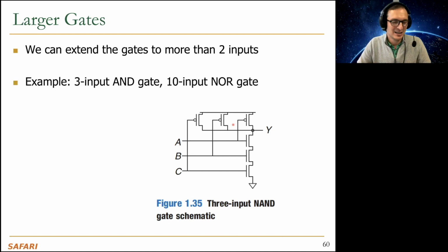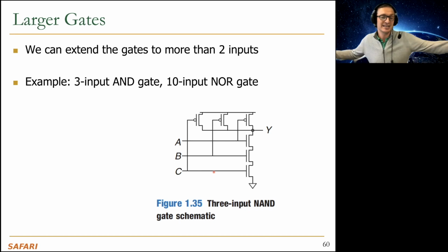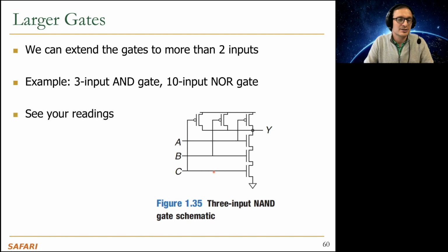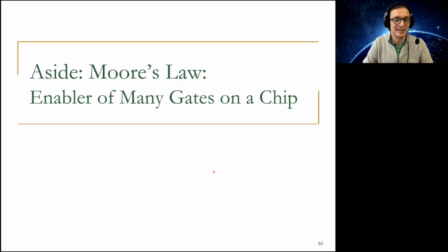Keep on adding. Of course, the downside is that it becomes slower as you keep adding more inputs. So sometimes it's better to construct multiple-input NAND gates from multiple smaller-input NAND gates, as opposed to building one large 10-input NAND gate, for example. Okay, so see your readings for more gates.